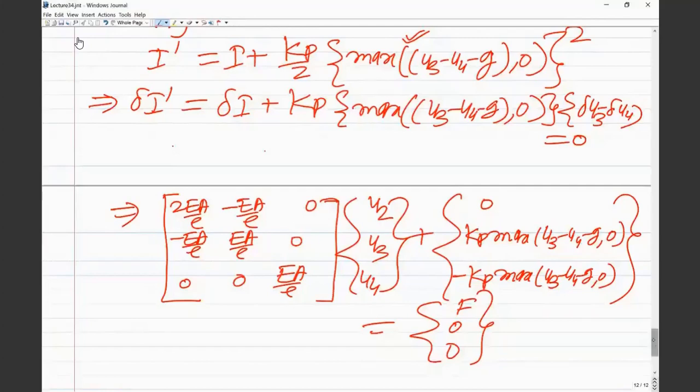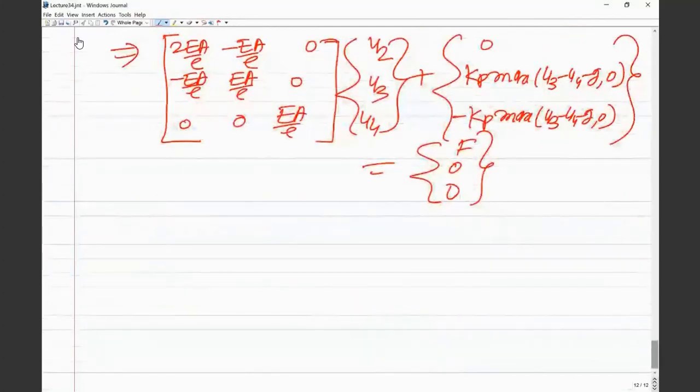So these are a few typical things; we have seen a very simple way of solving the problem. Then we have introduced the minimization of the total potential energy functional with a constraint, then the Lagrange multiplier and penalty approach, then posing both the cases, f less than or equal to f star and f greater than f star, into a single problem. And then we have seen how the Lagrange multiplier method or penalty method are used to solve this problem. So I think this is where I want to stop, and I will just give you another problem to try, although I will also discuss this in the next class.